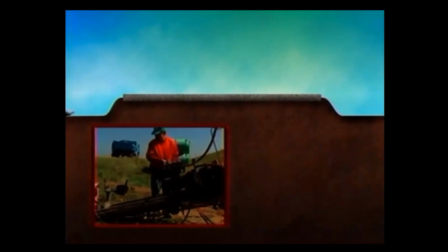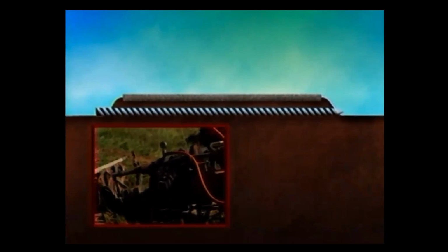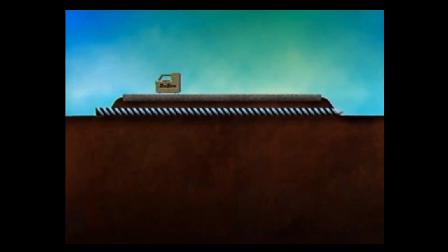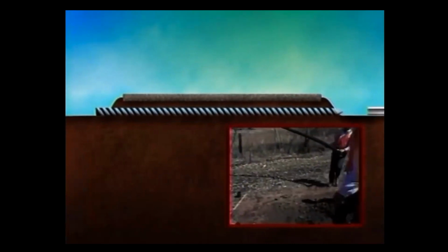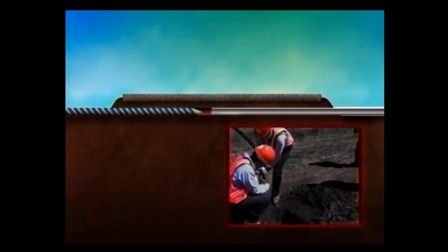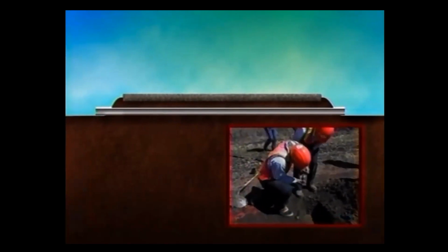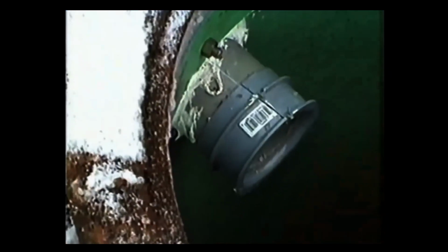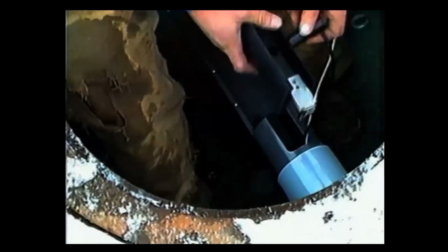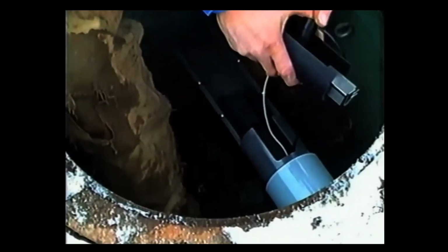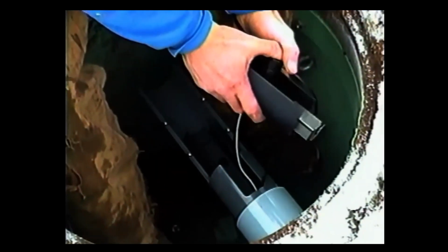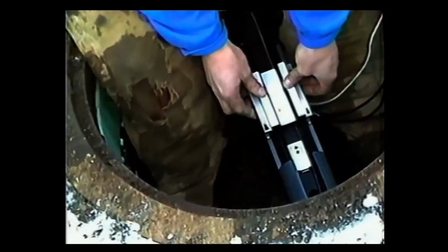To install the protective conduit for the non-invasive microloop, use standard horizontal directional drilling techniques. Depth tolerances can easily be maintained by locating the drill head every 4 to 6 feet. Place a 3-inch PVC or seamless poly conduit 18 to 24 inches below the road surface, with the conduit exiting into a handhole. Once the conduit is in position, place the probe in the carrier end piece. Measure the distance between each probe for exact placement. And insert the carriers and probes and lock them in place.